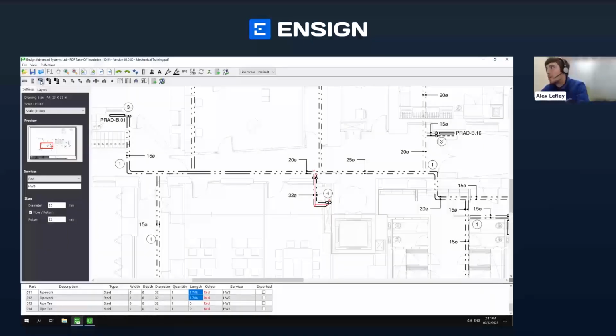I'm going to go back with straight with bends. I'm now going to go over to the left. So I'm going to change my pipe size here to 20, and then left click, right click. Once again, if I want to do the T now, T, click, click, done. Change my pipe size down to 15, straight with bends, left, left, left, right. That's the idea, okay?